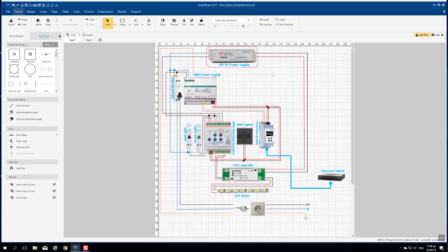And channel C will be used to control the AC power needed for the 24 volts DC power supply of the LED stripe. The power supply will take the neutral from the circuit breaker.